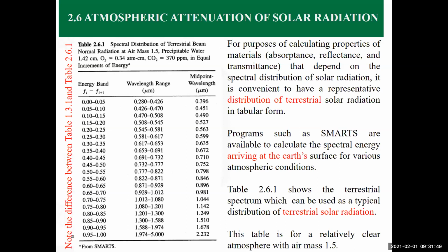And transmittance, basically transmission, is something through the glass. When you have something covered with glass, you need the solar energy to penetrate through the glass to the inside, so the glass transmissivity has to be high. The summation of the absorptivity, reflectivity, and transmissivity is equal to 1. A black body, which is a special case, would have absorptivity closer to 1, and the reflectivity and transmissivity each almost approaching 0.